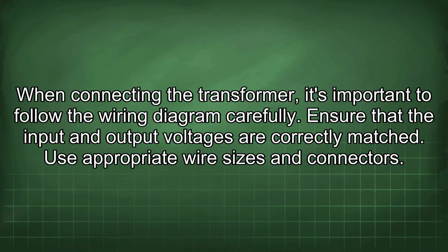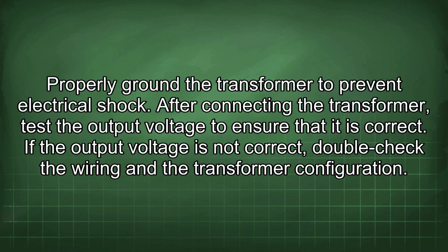When connecting the transformer, it's important to follow the wiring diagram carefully. Ensure that the input and output voltages are correctly matched. Use appropriate wire sizes and connectors. Properly ground the transformer to prevent electrical shock.